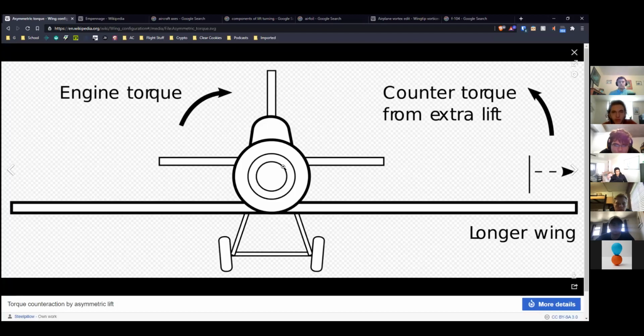The idea behind this at first actually seems like a really good idea, at least on a propeller-driven aircraft, because all propeller-driven aircraft have a motor that spins to drive that propeller, and the combination of the motor and propeller spinning is basically a torque on the rest of the plane. If the plane wasn't a plane and it was just a tube, the tube would spin exactly opposite to whatever the motor spun, and you wouldn't get very much power out of the motor.